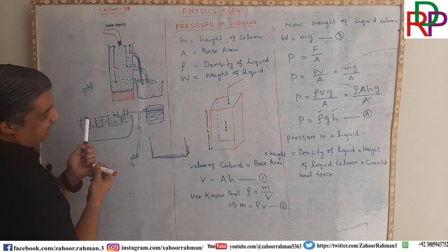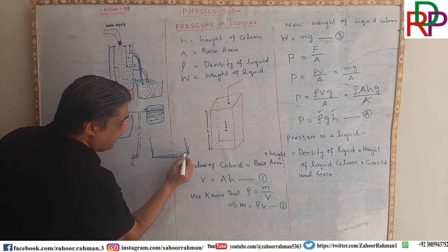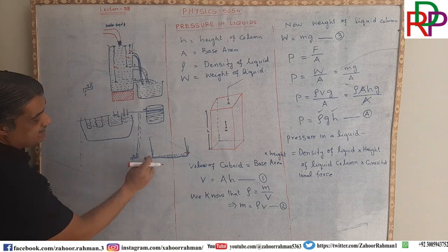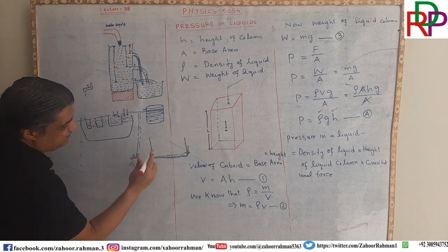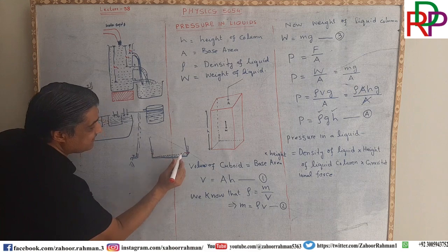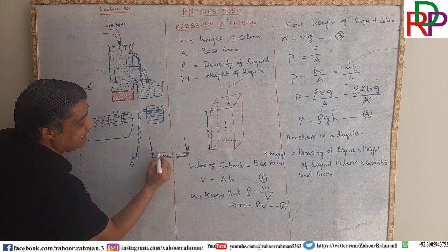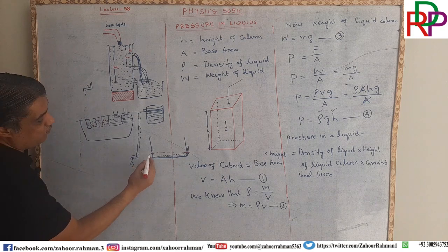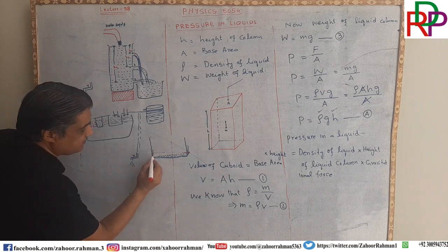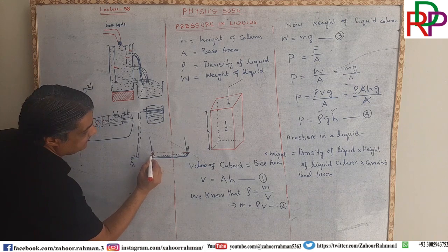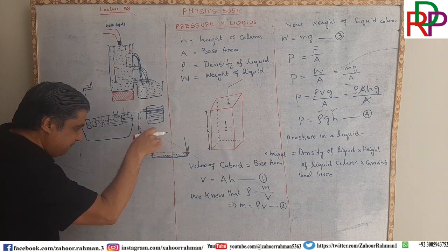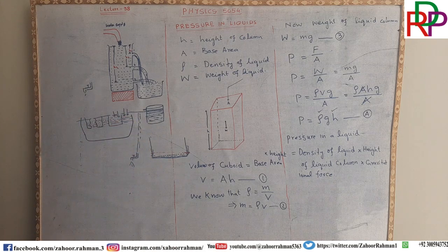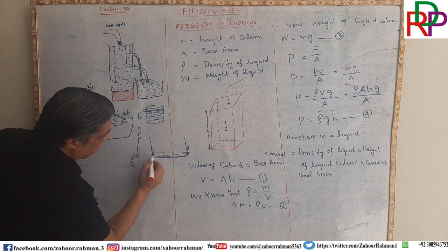On this side, they are marking a place like this, and on this side, which is a bit reduced, first they are saying that this is the flat level, no slope is there. Then they are reducing it, saying 1 inch or half inch of slope should be there. So they are putting the pipe level down and marking it.